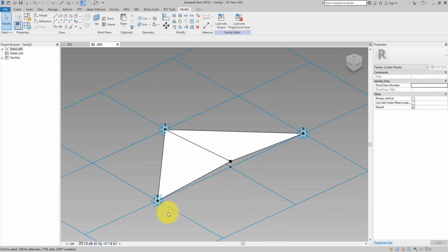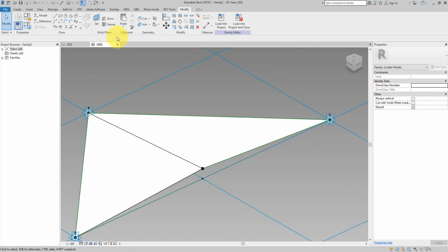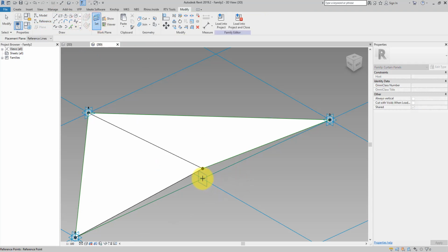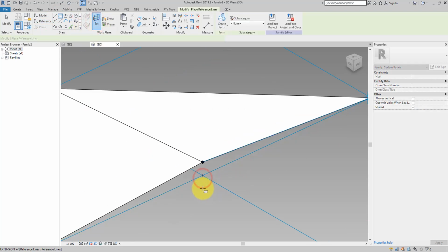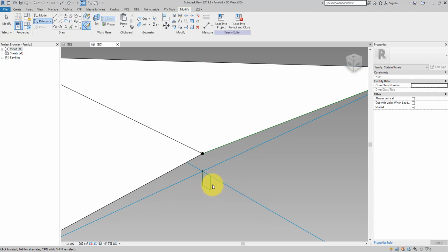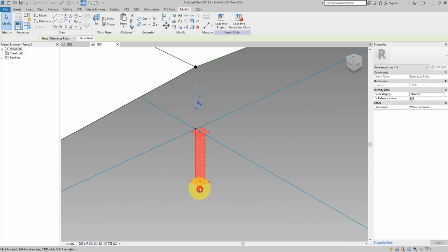Anyway, don't forget about the frame because there's a frame there as well. So let's now drop in here a reference rectangle on a work plane that I can set to be this vertical one. Let's draw it firstly from the corner there. And maybe this can be 20 mil. And this other one can be 40.